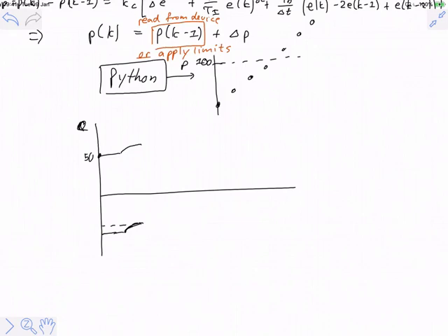And so you would notice how this works by, let's say we make a step change like this, and we saturate the controller, right? And even after the controller is saturated, the temperature will still continue to rise, right? But if we're at some kind of high set point, we'll be winding up in that case.